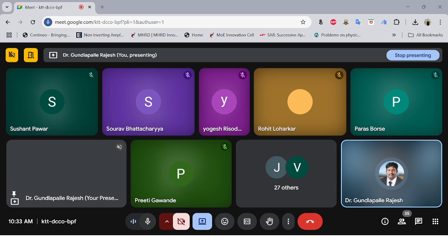I2C is a two-wire protocol where SDA and SCL are used. It is based completely on the master-slave approach. Then we have the SPI protocol, which has four wires: master out, slave in, master in, slave out, then the serial clock, and SS. It operates in full duplex, which is faster than I2C. This SPI protocol is usually used between ADCs, that is analog to digital converters, memory chips and displays.